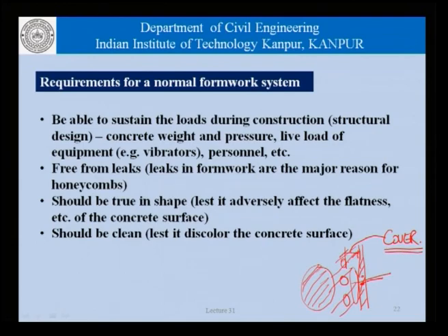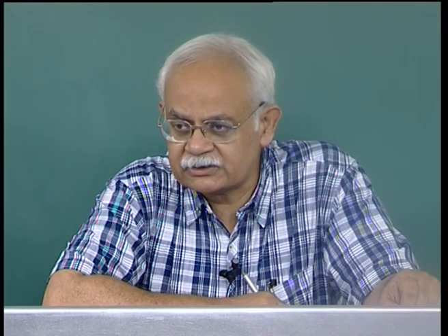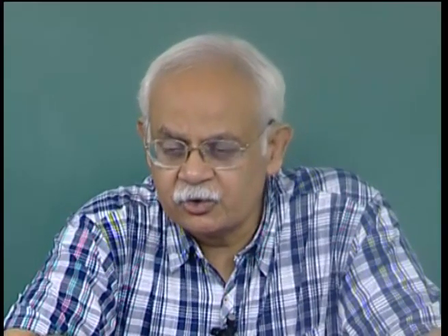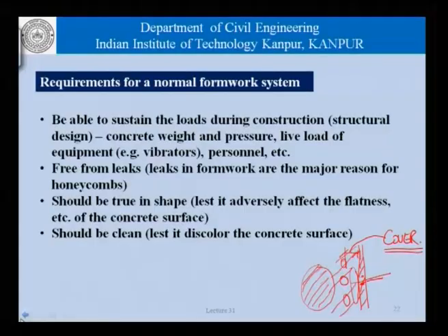Conversely speaking, therefore, if we want durable structures, we need to have good quality cover concrete, and in order to ensure good quality cover concrete, we need to have good quality formwork, and that is what gives rise to special formworks and a whole lot of discussion relating to that aspect. Some of it which we will briefly discuss from this point onwards.